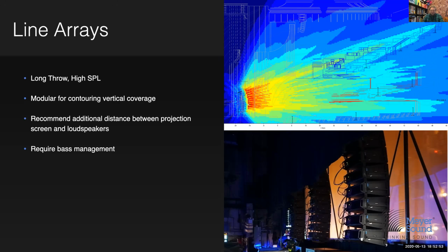So that was challenging, but line arrays, you can fly them out. They're already hanging. So in this one, I had kind of a unique opportunity with a line array design, in that typically I could not put line arrays this low, especially on stage. It's where the band would be, right? So this was a fun opportunity to get to say, this array will work great if you hang it low, basically 4 feet off the ground, essentially a super tall ground stack, but hanging.